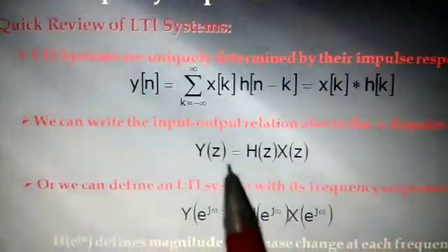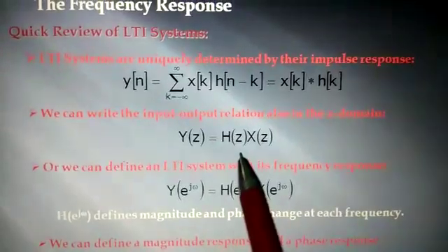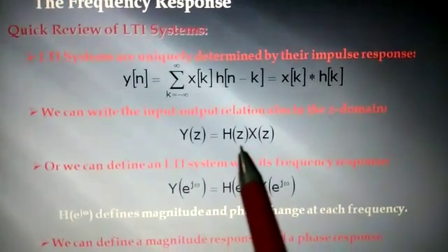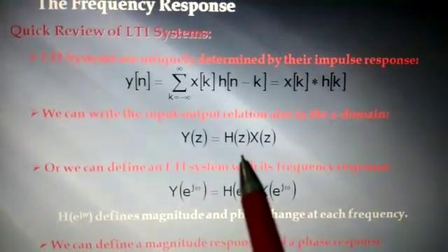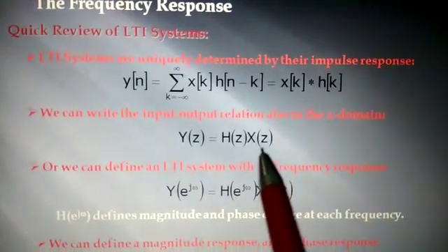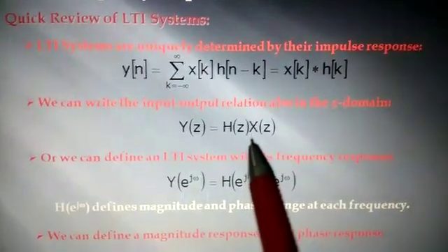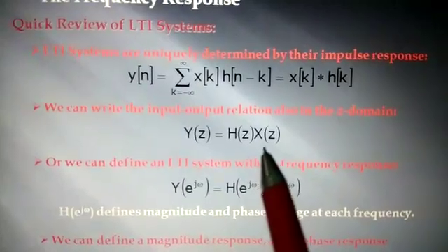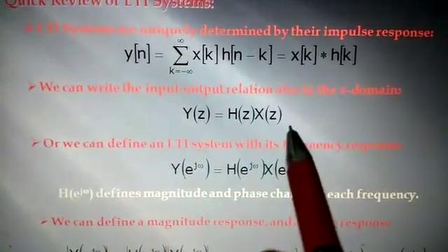So this is called the Z transform. Any digital filter, whether it is an IIR filter or an FIR filter, can be represented with a transfer function H(z). Digital filters are always in terms of the Z transform, while the analog filter is represented by the Laplace transform, and there is a relation between the Laplace and Z transforms also.